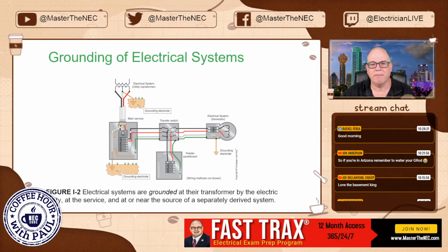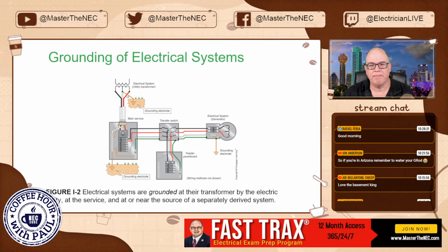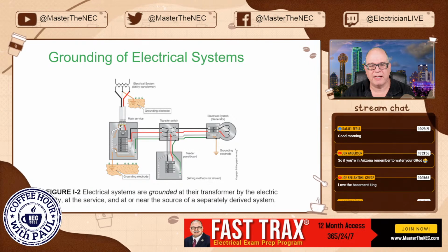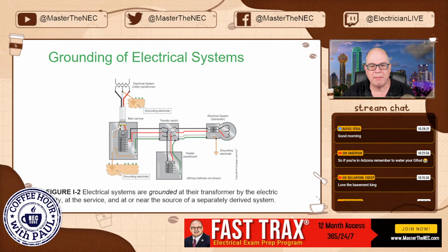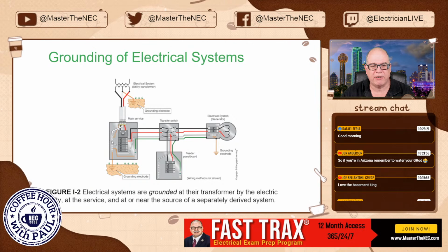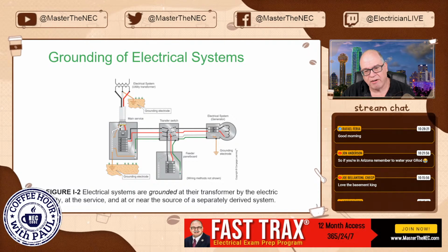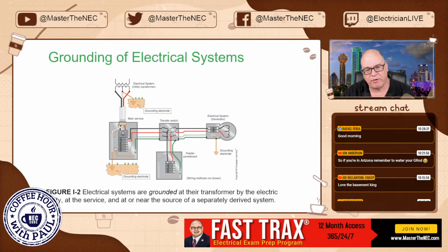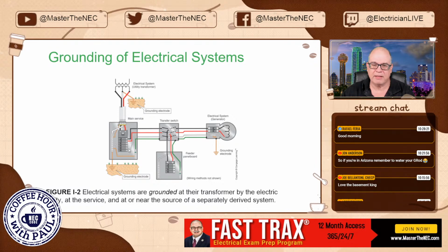So in this case, we have the connection right here. This is a grounded system, a grounded conductor intentionally connected to earth. On the service, you're required to bring in the grounded neutral conductor. Here's our main bonding jumper, connecting both the equipment ground and the grounded conductor. Phil likes to show them separate, but they could be all on one bar, and this main bonding jumper could be installed as a green screw on the main bar. Since you do separate them, and that's perfectly okay, this jumper is also the main bonding jumper that connects both the equipment ground and the grounded conductor together. You would size this based on 250.102(C)(1), but we're getting way ahead of ourselves at this point.